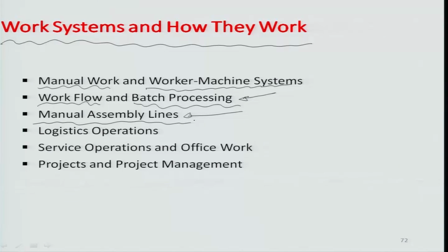For example, let us say when we talk about again a car line, and when we talk about painted body storage, the painted bodies which go into inspection and repair are basically on trolleys. They are no longer on an assembly line, and these trolleys are all chained together, and you could push those trolleys between the different inspection stations and repair stations, because the associated problem with paint repair is that the time scales are not known.